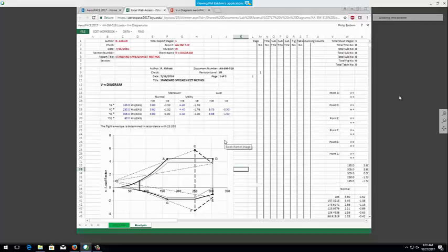So I went through and created a different set, defined a minimum and maximum for each of the variables, ran about 1,008 different points, and from that created a model. We can see graphically here a series of sensitivities. Basically, each of these are partial derivatives with respect to that particular variable. So we have the wing loading in PSF, and then the CL during the launch, which I called CL max.